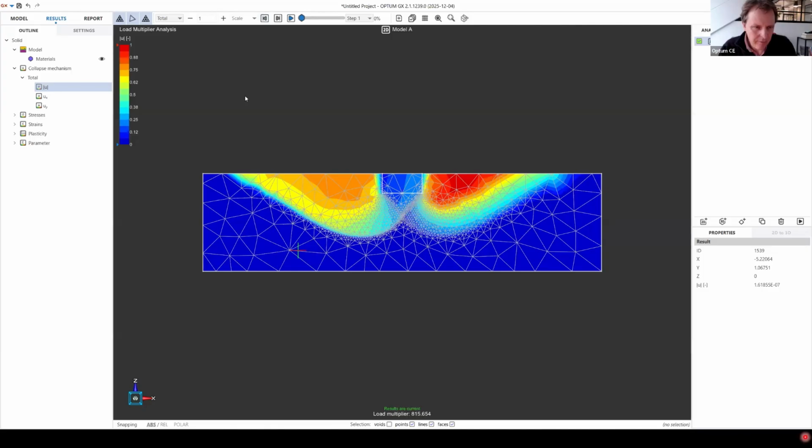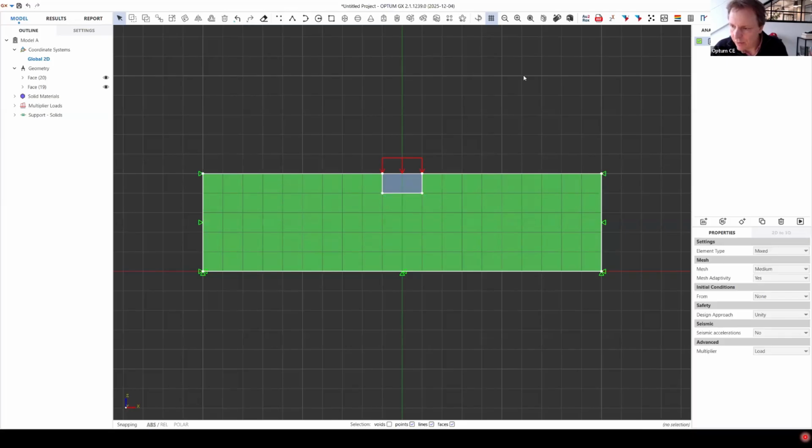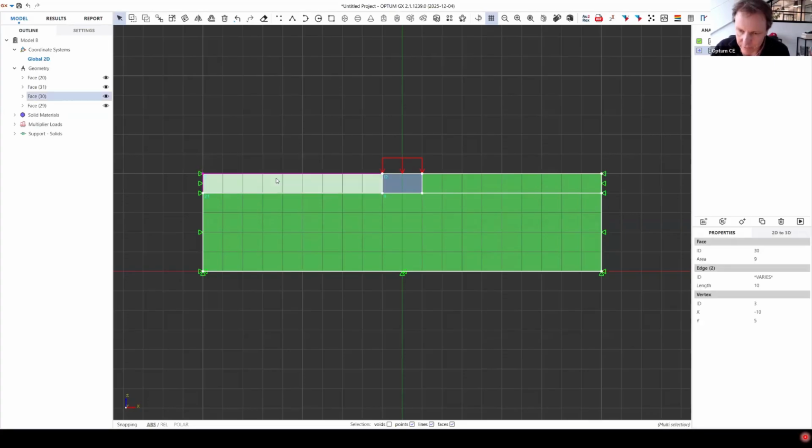And then the first problem I mentioned on the list is this issue with embedment, because the way the codes work, at least Eurocode 7, and I think most other codes, and kind of the way Terzaghi's bearing capacity equation works as well, is that you always make reference to the base of the foundation. And then you might have some soil here next to the foundation, and you kind of assume that the weight of this acts here,